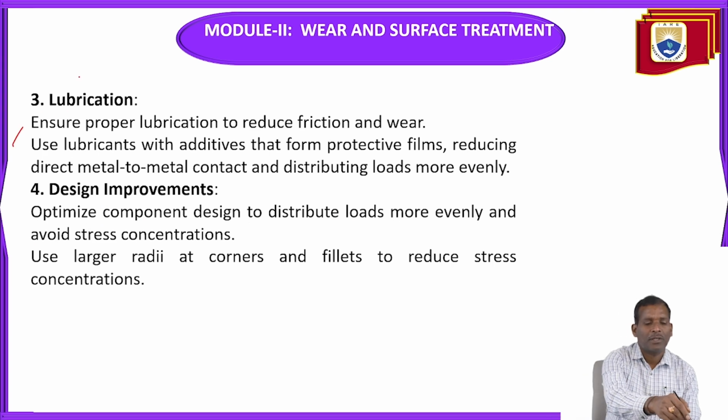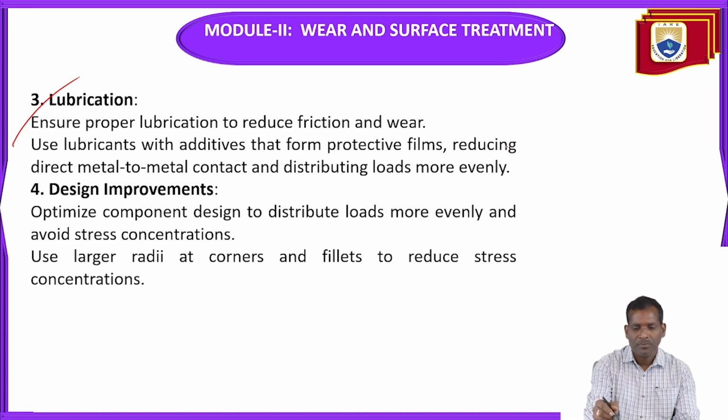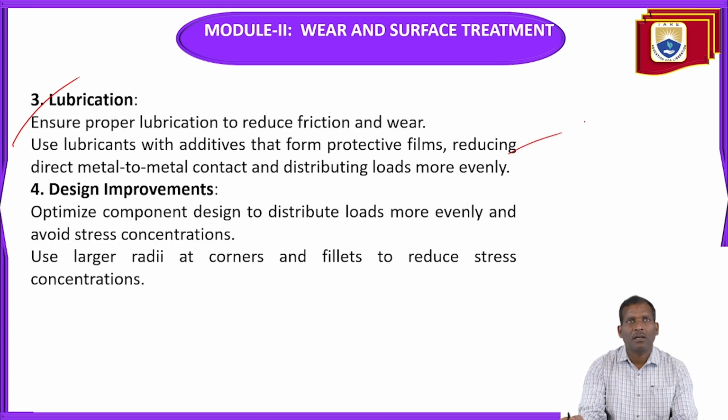Next, the third one is lubrication. Ensure proper lubrication to reduce friction and wear. Use lubricants with additives that form protective films, reducing direct metal to metal contact and distributing loads more evenly.